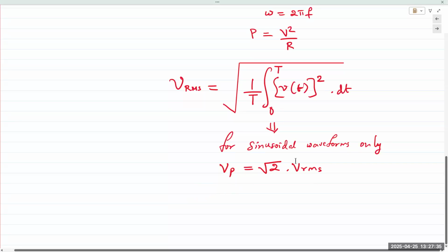So to determine the peak to peak values of our power outlets, you have to take 120 times 2, 240, and 240 times √2. Sorry, √2 times VRMS, so √2 times 120 times 2. So 2√2 times 120. That's a swing of over 350 volts. Okay, swing of 350 volts.